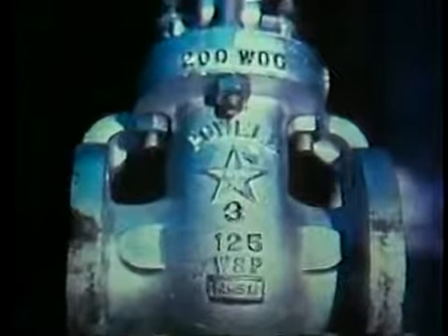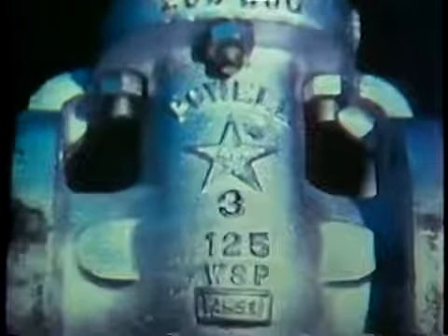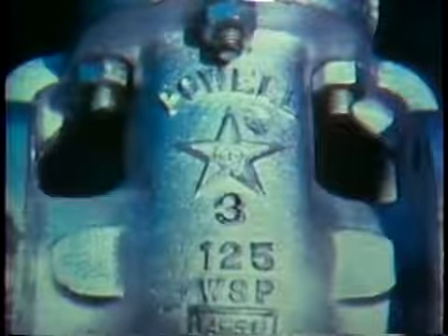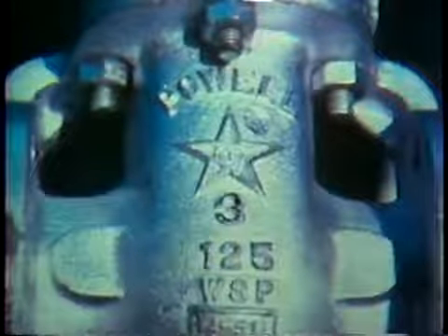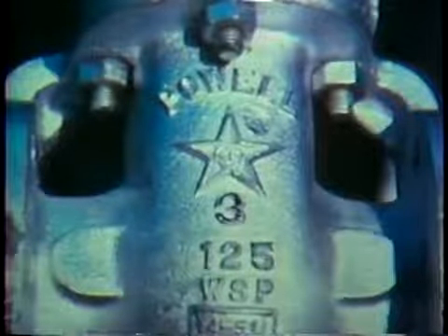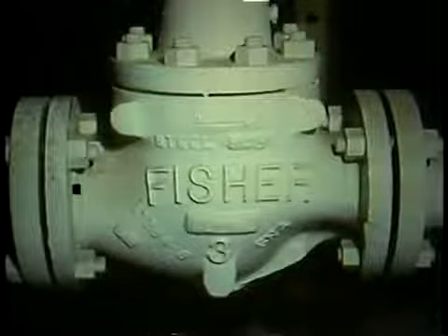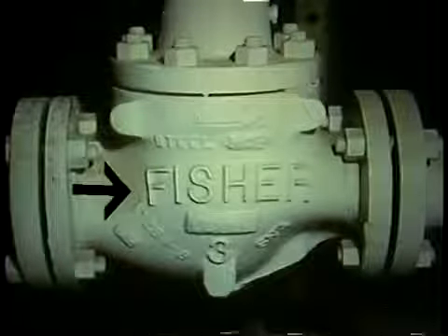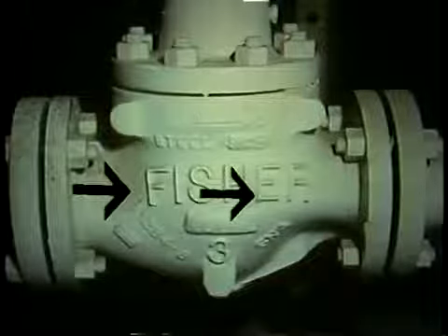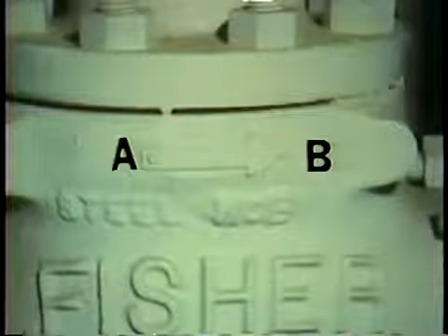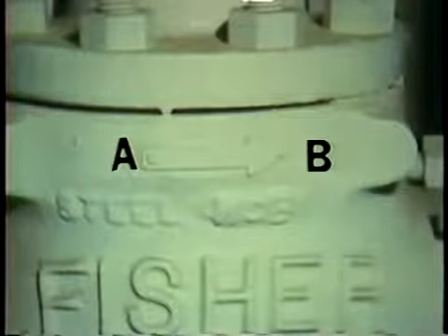You see here bridge wall markings. They provide very useful information. They indicate how the internal parts of the valve are arranged. By knowing how the parts are arranged inside, you'll be able to tell how the disc closes on the seat of the valve. Bridge wall markings on this valve show that flow comes in from the left and then passes through the open area of the seat to come through this outlet. An arrow or set of letters also may be used to show the direction of flow through the valve.